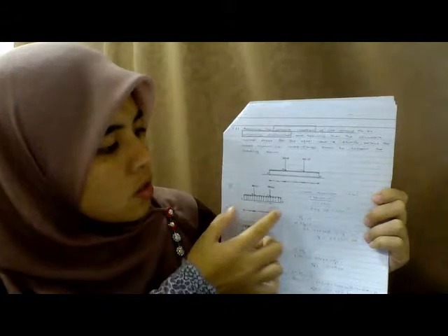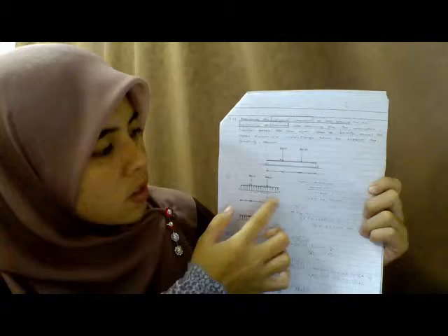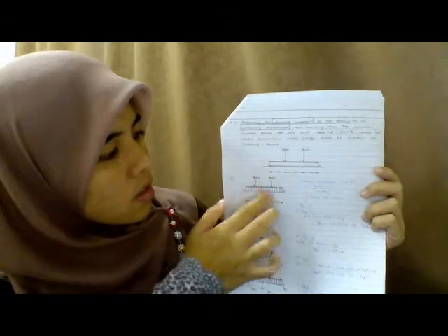So the first step that we need to do is we need to find the free body diagram, which is that the question stated the upper reactions of the ground is uniformly distributed, which is in here there is the distributed loading force, which moves upward. So the step is also same with the earlier questions. So we just use the summation of Fy equal to 0.